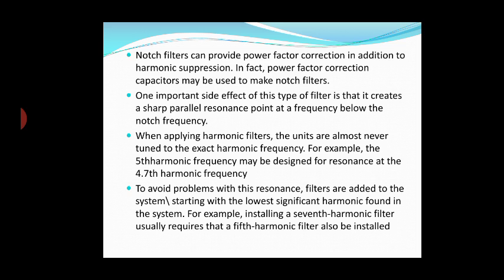The one important side effect of this type of filter is that it creates a sharp parallel resonance point at a frequency below the notch frequency.